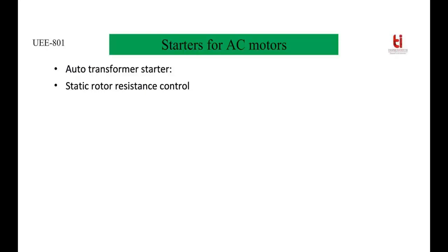Static rotor resistance control we have discussed already in speed control of 3-phase induction motor, so you can see that lecture class. This is suitable for slip ring induction motor. Basically, rotor resistance is kept high to develop high starting torque. Once the motor starts, then the external resistances across the rotor are reduced.